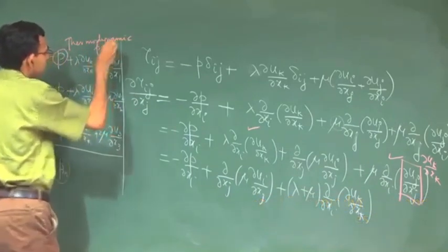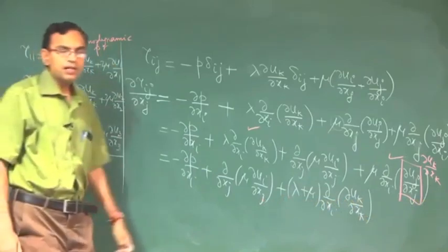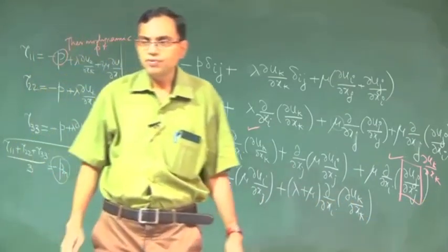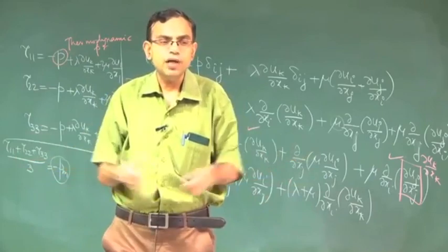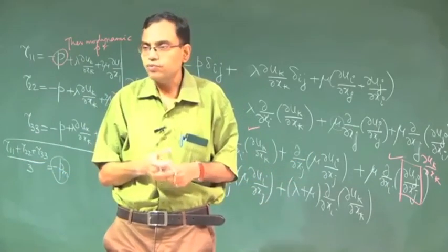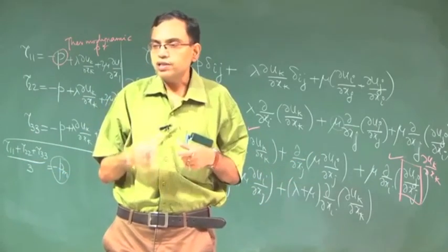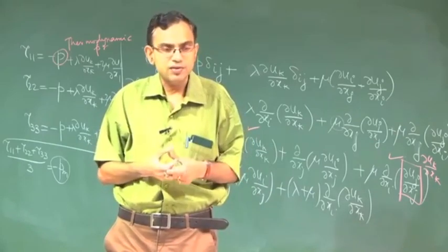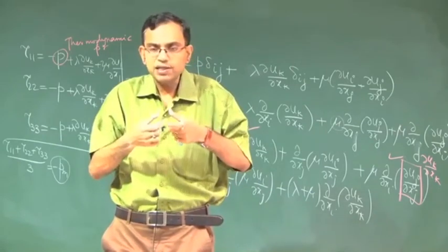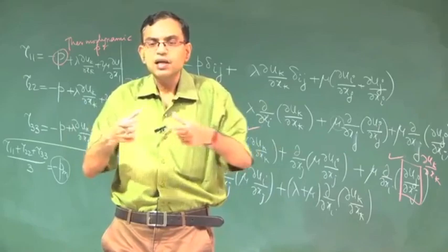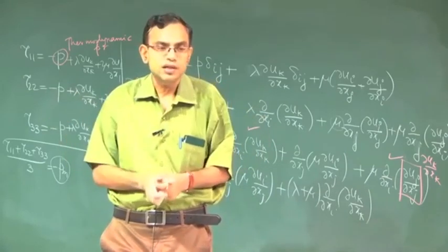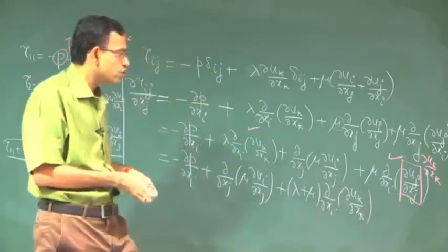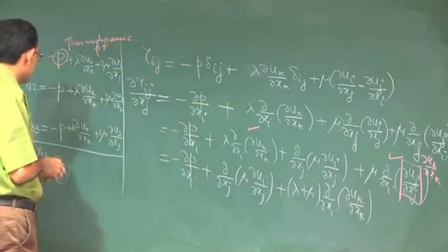What is the difference? The thermodynamic pressure will have all possible degrees of freedom of molecules embedded within it: rotational, translational, vibrational, etc. And the mechanical pressure is a manifestation of all these eventually converted into translational degrees of freedom. So, that is the basic difference.